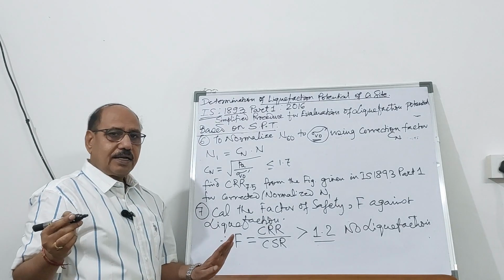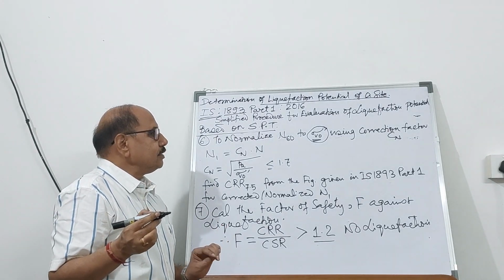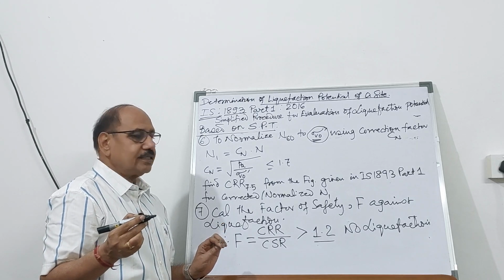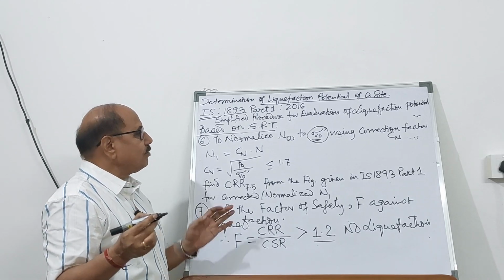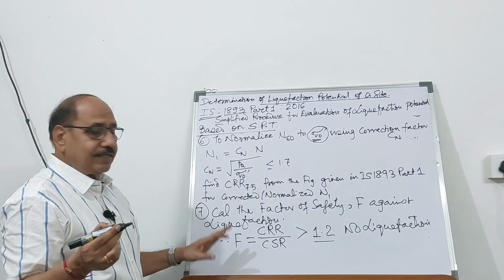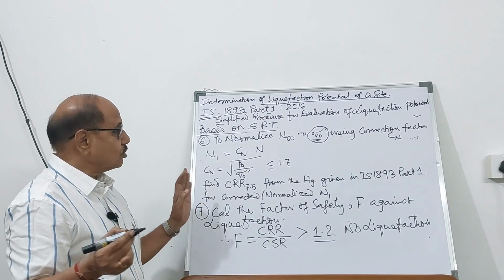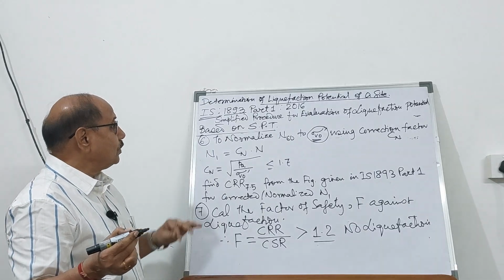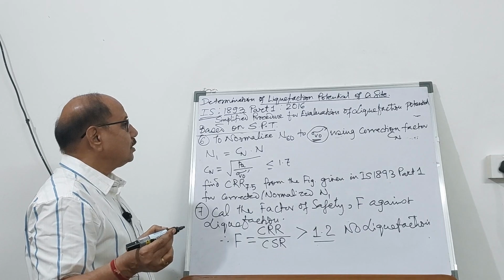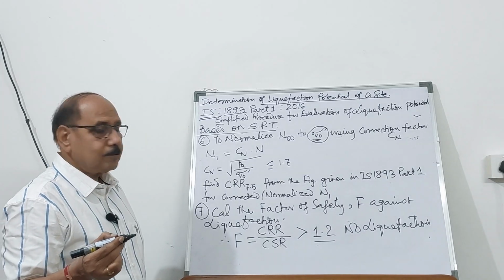So, for any site engineer or any civil engineer, a structural engineer, whenever you are going to construct a structure, it is mandatory in India and across the world now to find out the liquefaction potential of a particular site.